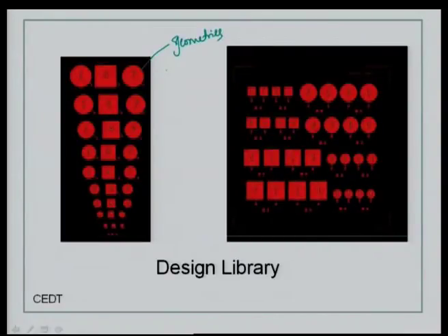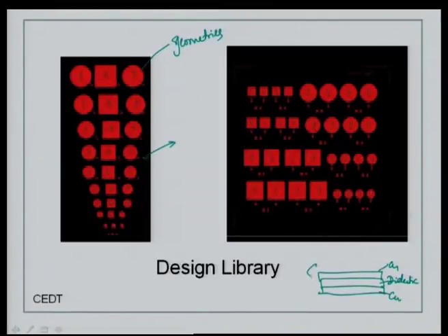Here you have a circular geometry, a square, and you can also see there is a micro via interconnect that could be seen here. So, basically you are looking at a metal layer and then a sandwich material, which is the dielectric that we are talking about, and then again the other copper layer. So, these kinds of structures can be created on your printed wiring board.